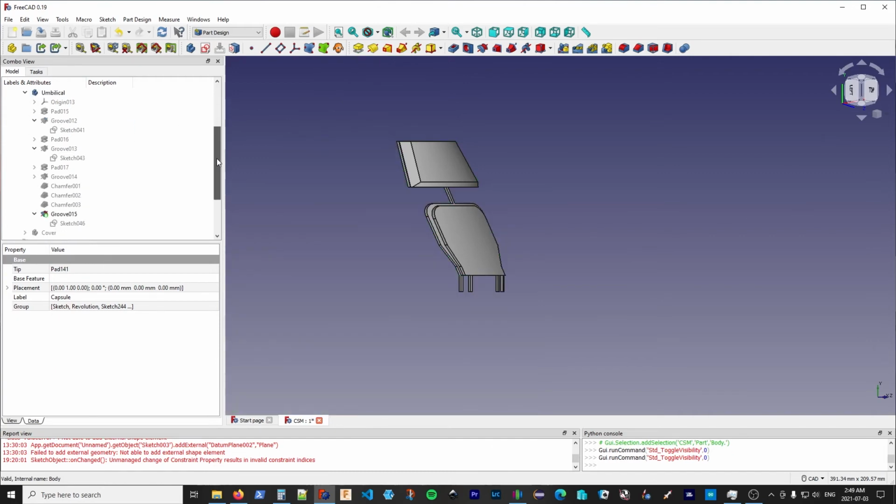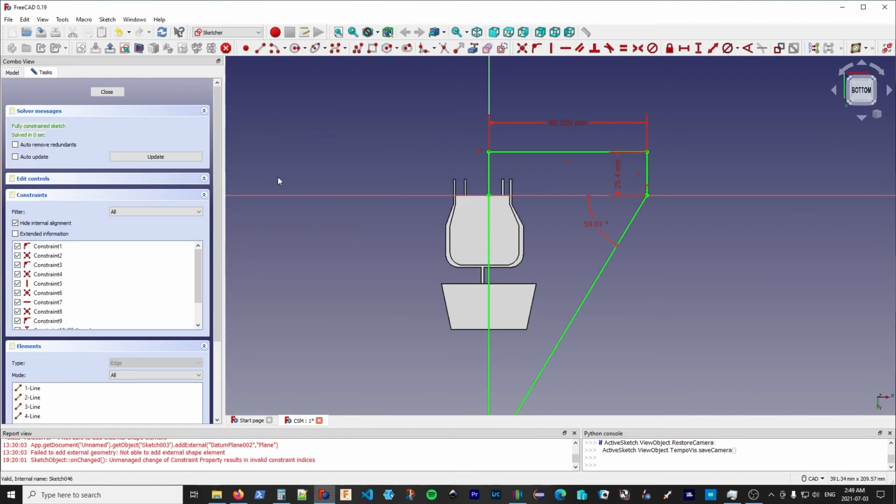So when you're doing this final groove, that line should be slightly inside the edge of the nose cone. So what you're doing is you're extending the piece a little bit into the nose itself. It doesn't have to be far. A fraction of a millimeter is fine. But you will find if you line it up perfectly, like you would with some other CAD packages, then you're going to have some bizarre errors and you're not going to understand why. So just back it into the piece just that little bit and things will merge fine.